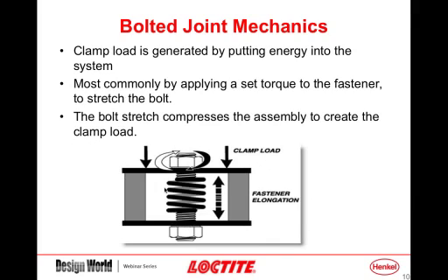A little different representation of it is in this next slide, where you can see that tightening that we've done on the fastener is actually stretching the bolt. And here we're using a spring kind of as a metaphor for that fastener, where once you've applied the specified torque to the fastener, you've stretched the bolt, and you now have a spring force that's holding your surfaces together. And if we take this lower nut here, I'm going to go to an exploded view of it.